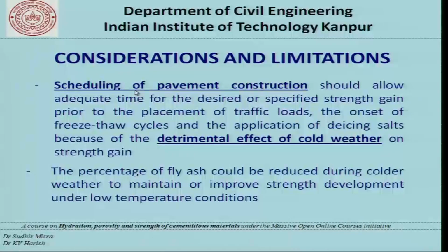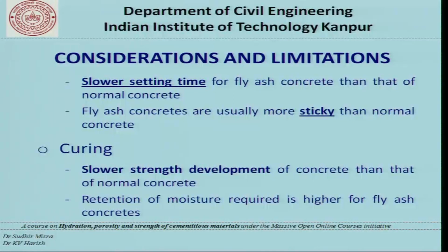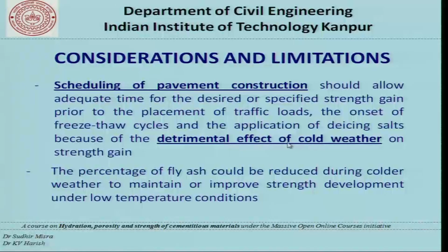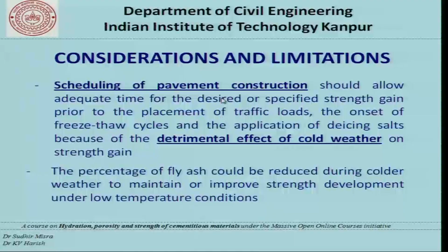And this curing could be a problematic case not just for normal weather but even for cold weather. If you take cold weather, the hydration takes place very slowly. In that case even the cement hydration goes very slowly, and such mixtures have very low strength at early ages, say between 1 day to about 3 days. In such cases we need really higher strengths, and addition of fly ash is not usually preferred under such circumstances.